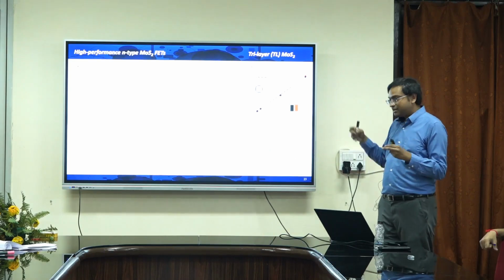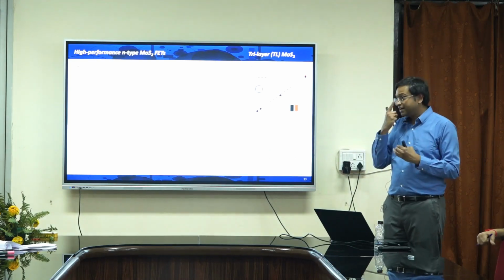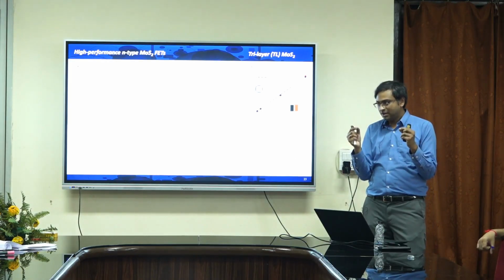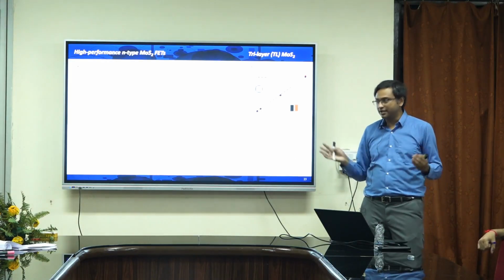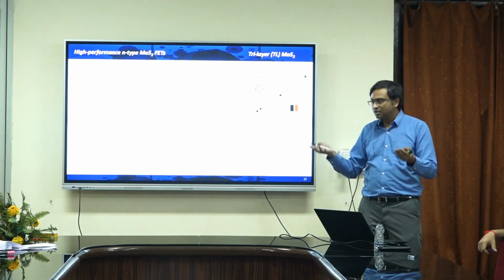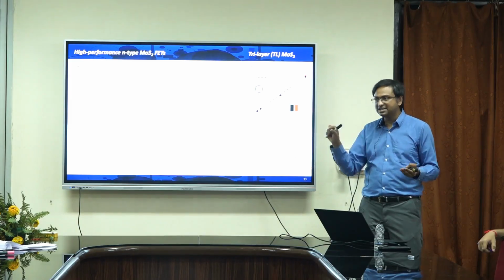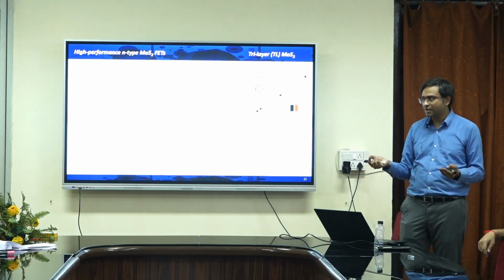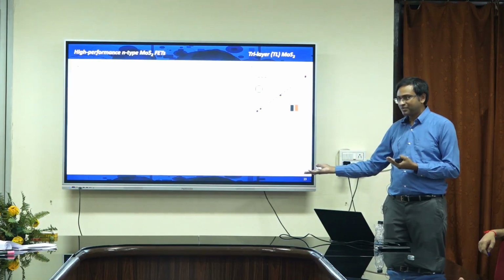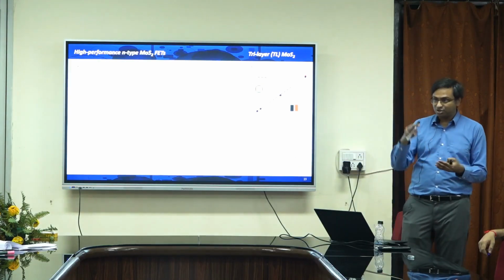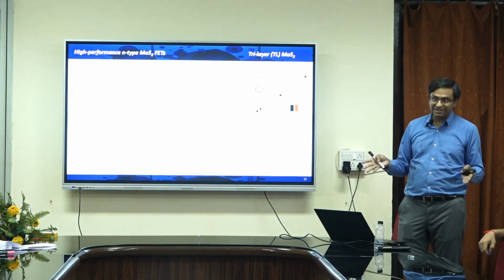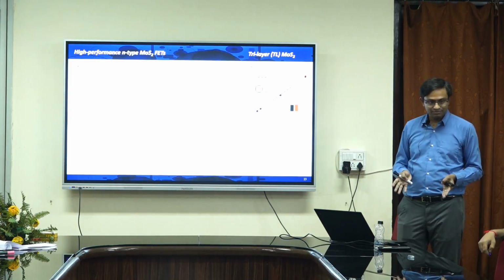But the rule for the IRDS is that your channel material has to be less than 2 nanometer thickness. So you can say, okay, why don't you go to 10 layers? If I go to 10 layers, then the thickness of the material becomes 6.5 nanometer, because each layer is like 0.65 nanometer. Then I should not use it, because silicon is already 6 nanometer. So the IRDS requirement is your channel has to be thinner than 2 nanometer, which means it has to be 2 or 3 layers. That is still allowable.